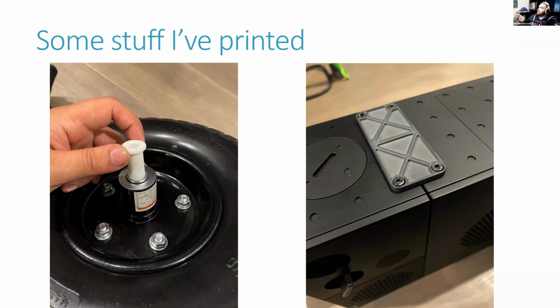STL is a mesh file format that is made up completely of triangles. You're not allowed to have curves. Well, if you look at my parts, those are clearly curves. So either I'm BSing you or there's something else. It's the second thing. So in order to get a curve, you just get a bunch of tiny triangles. In SolidWorks, there's actually an option to set how many triangles you want to use.